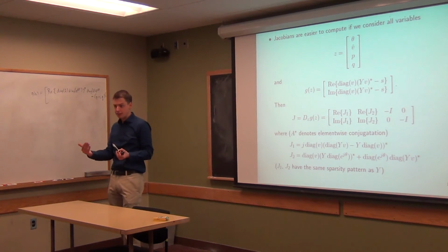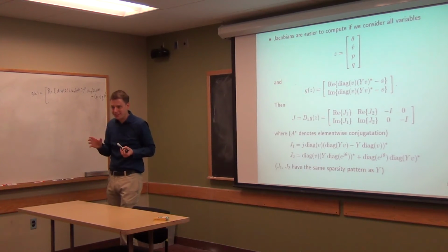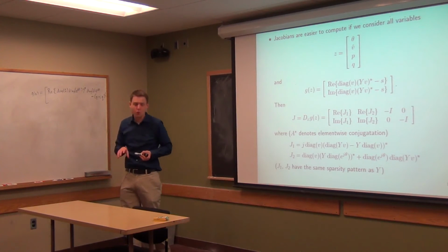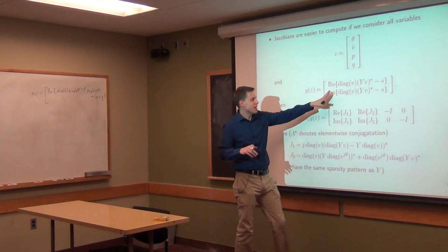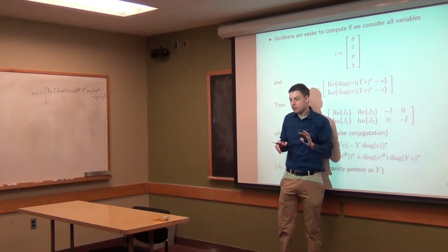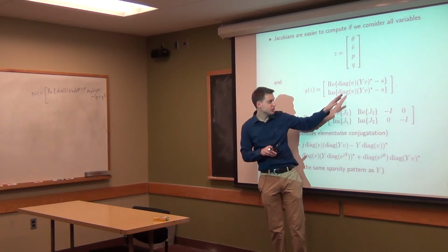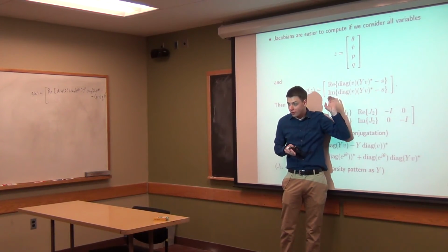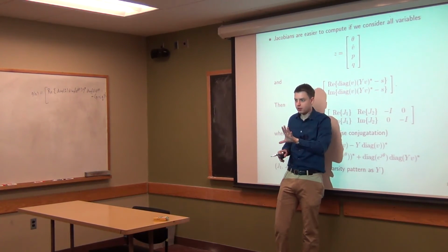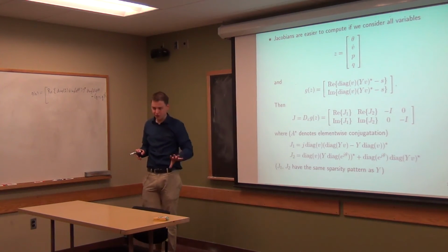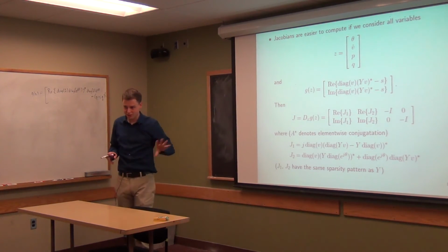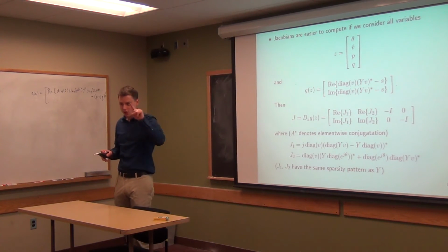In the intervening steps, these are just numbers. And it really doesn't matter until we have computed the solution what those numbers are. So what the Jacobian is physically is sort of weird, because the function isn't anything but the power flow mismatch. Now, the Jacobian of this function when the function is equal to 0, so when we've solved it, we can again compute Jacobians then. Those are not 0. The Jacobians when this function is equal to 0 have physical meaning.